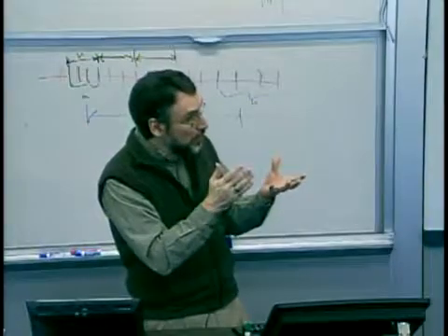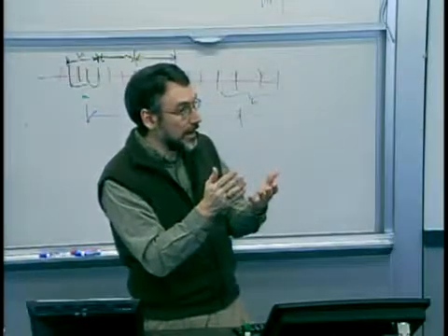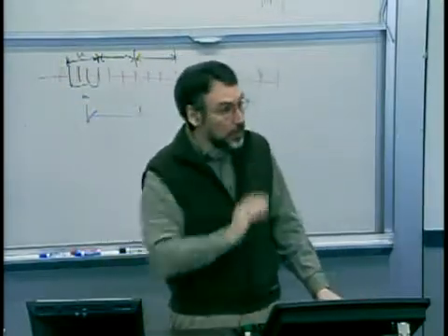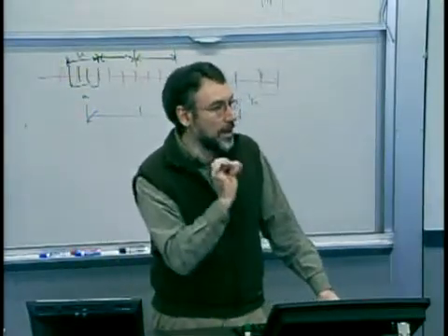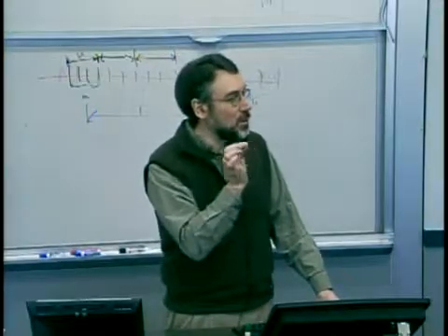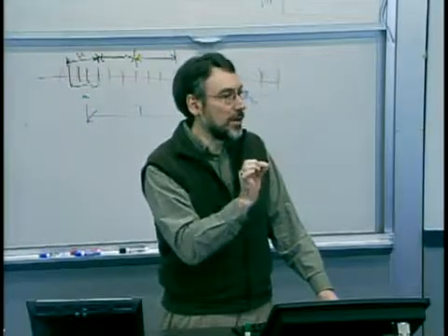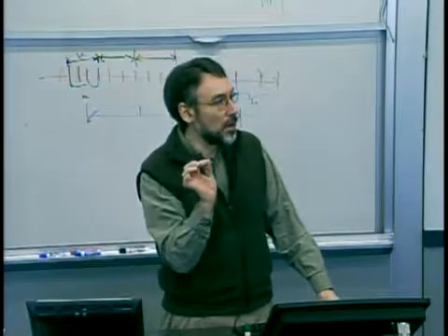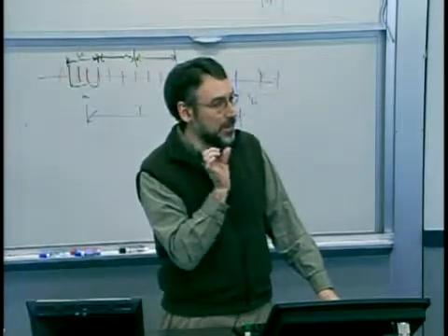So that's again another multivariate question, looking at how important it is for two parameters to be close to each other, even if one or the other could deviate. It's okay if they both do. And so what I would do is, if the importance is the difference between those two dimensions, that's what I would characterize, and that's what I would chart, and that's what I would set my spec limits on.